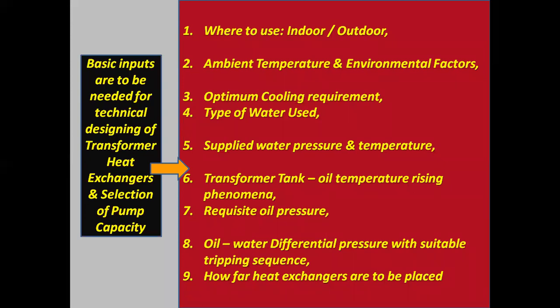Basic inputs are needed for technical designing of transformer heat exchangers and selection of pump capacity. One, what to use, that is indoor type or outdoor type transformers. Ambient temperature and environmental factors. Optimum cooling requirement. Type of water used. Supplied water pressure and temperature. Transformer tank oil temperature rising phenomena. Requisite oil pressure. Oil water differential pressure with suitable tripping sequence. How far heat exchangers are to be placed.